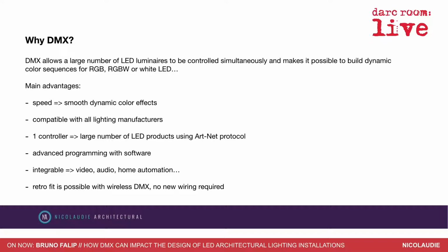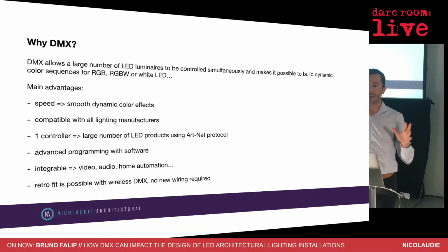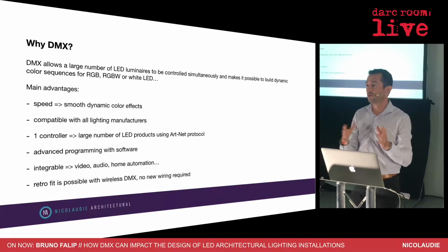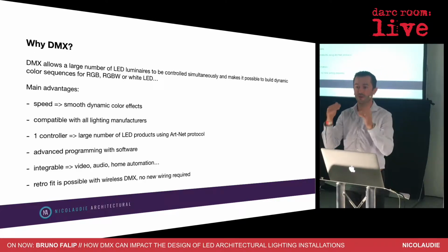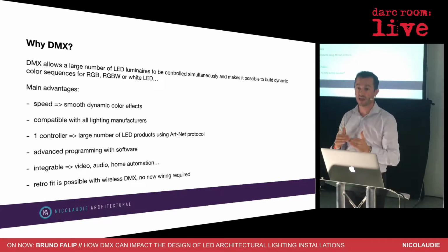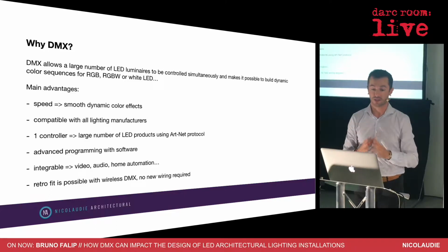You'll see some flickering. Because of this signal, you have the possibility to create some very smooth fades and have some nice color, because we are not in the live entertainment market. You don't want to have some fancy flashing. Imagine this is for a nice historical building. You don't want to play fancy colors. So you have to have very smooth fades, and DMX is the right tool for that.